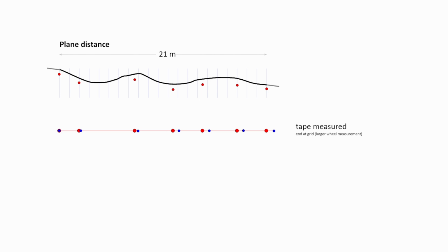The red dots represent the actual locations of the objects, while the blue ones are derived from our measurements. If we leave these measurements uncorrected, we can be certain that we'll encounter a measurement error that increases with distance. If we use the measurement from the first example, where we finish the profile relying on the reading from the measuring wheel, we'll achieve a similar effect. Only this time, the profile will simply be shorter. The localization errors will remain unchanged. One of the simplest techniques for correcting measurement errors is to rescale the measured length of the profile to match the length obtained from tape measurements.